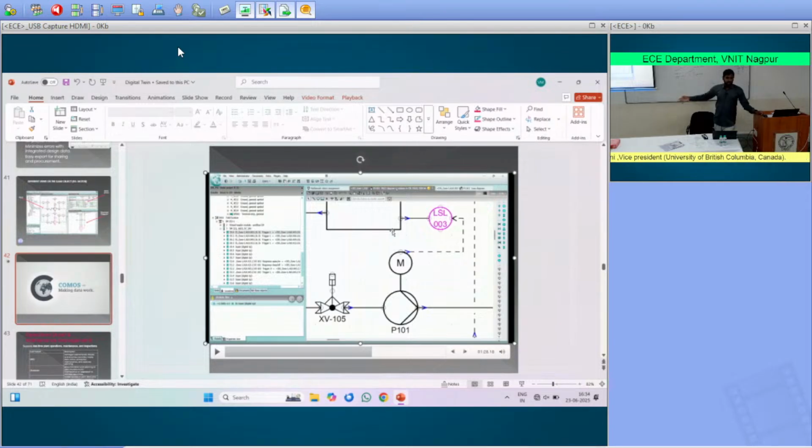It can run on any controller, like the Arduino you mentioned. Industries go with DCS, distributed control systems, or PLCs, and we can create a simulated mode for those too. With PLCSIM Advanced, a PLC is created in your PC itself, so you do not need any PLC controller like an S7-200 for your simulation. You can write programs and load them in simulation mode on your laptop, and through that run the SIMIT simulations.